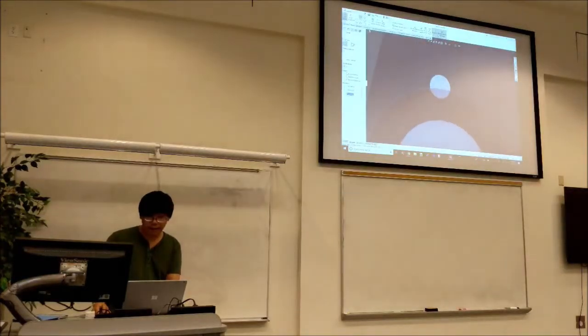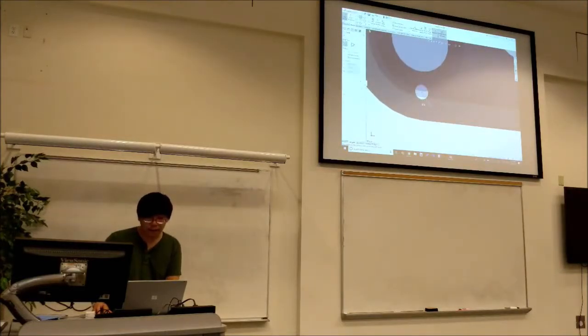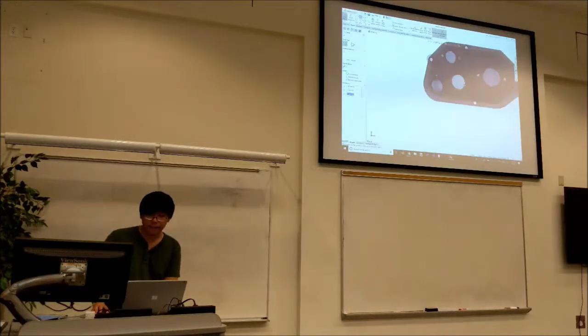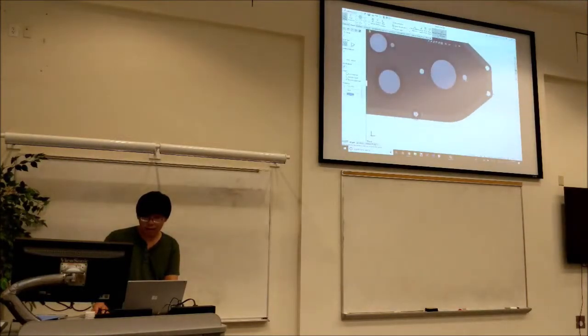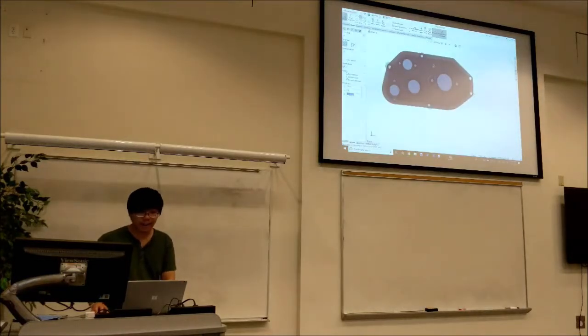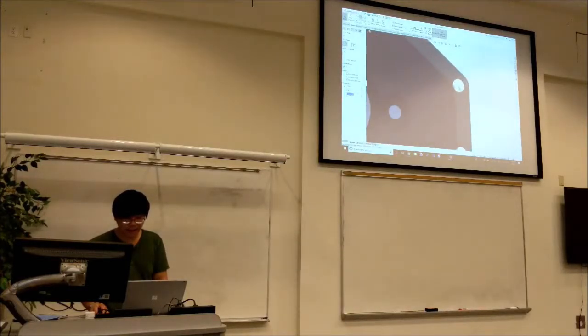So I'm not dimensioning anything yet. I'm basically just making circles on all these points, and then we'll go back in and set them to size, telling it how much of the material we want to keep. After that, we extrude all the empty space, and that forms the pocket. I think you guys can start to see why you shouldn't do this before your gearbox is done. It's really time consuming.